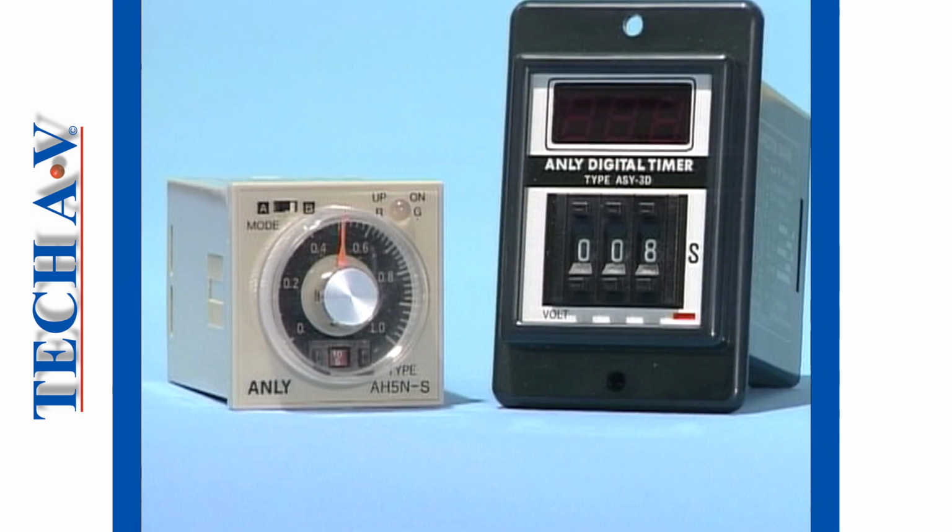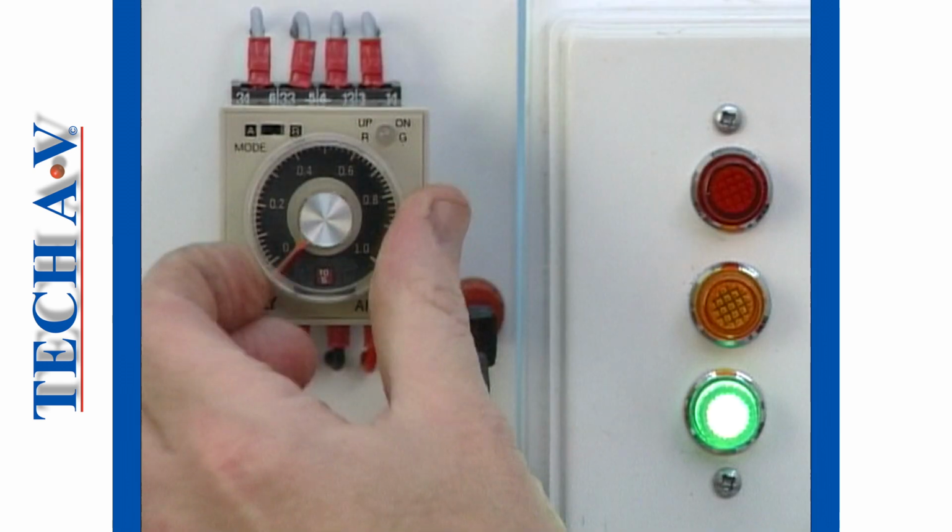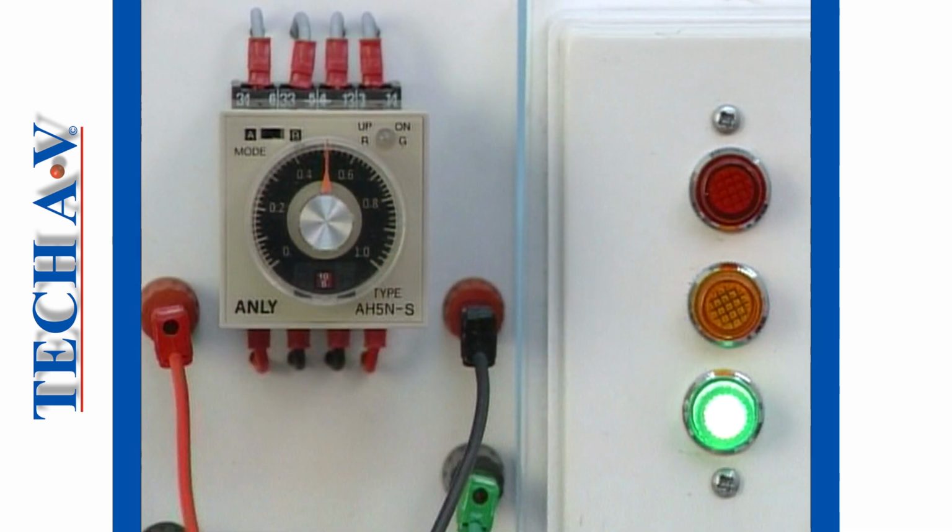The next important logic device we'll examine is the timer. Timers can be electromechanically or electronically driven, but regardless of mechanism, they both achieve the same objective, and that is to signal a change in state once a preset time delay has elapsed. After the timer has timed out or reached its preset delay, its contacts remain active until power is removed from the timer, whereupon it is reset, ready to begin another timing cycle.